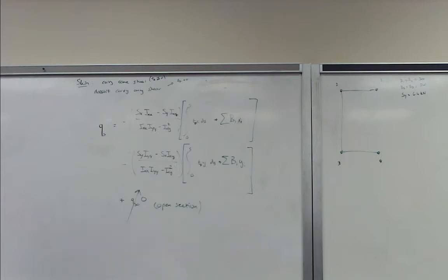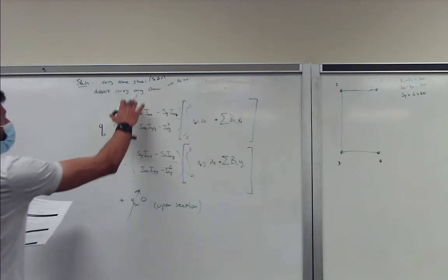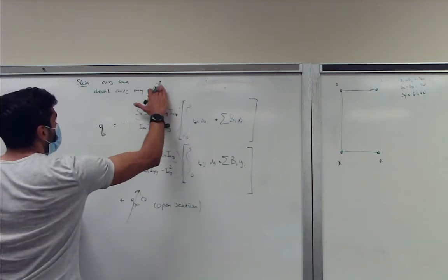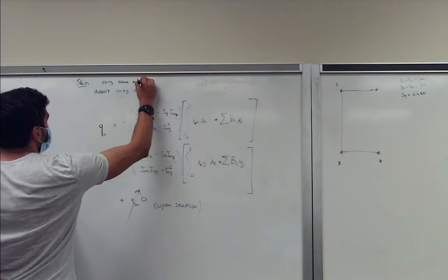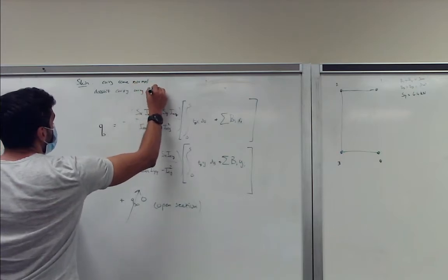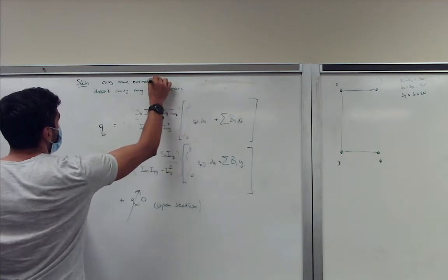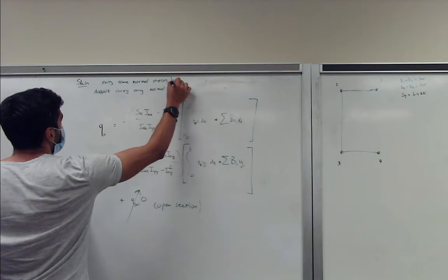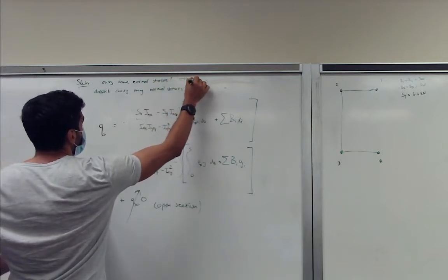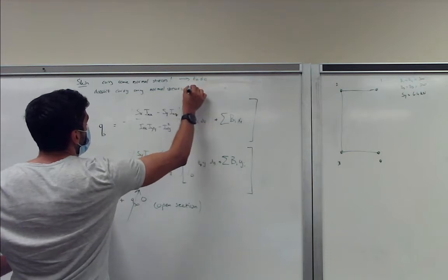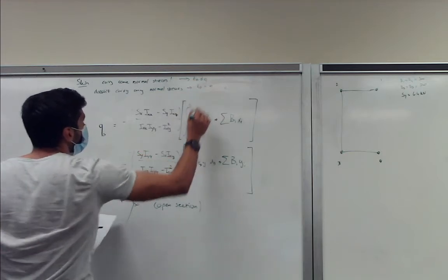And if you look at the slide, it says the skin is only effective in shear. Oh, sorry, this is incorrect. Some skins carry normal stresses, and some don't carry any normal stresses. A mistake on that. So if it carries normal stresses, tD is not equal to 0, and if it doesn't carry any normal stresses, tD is equal to 0.